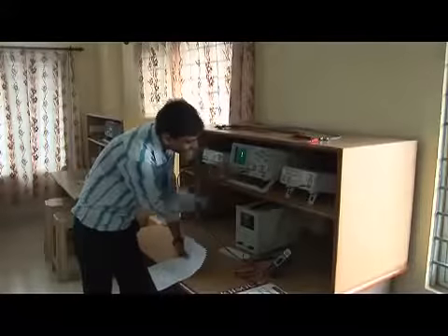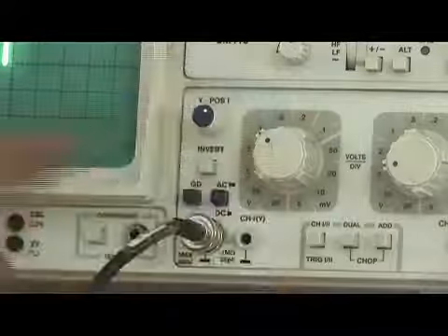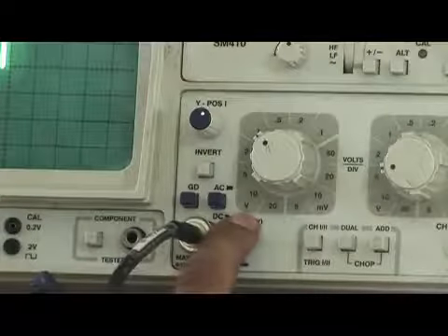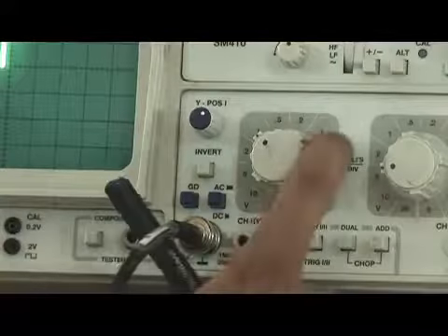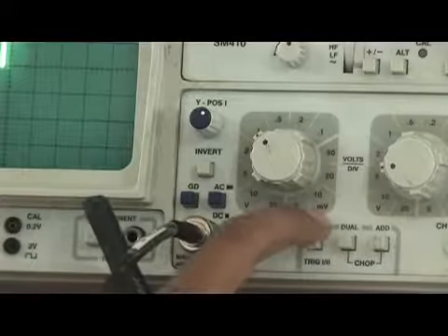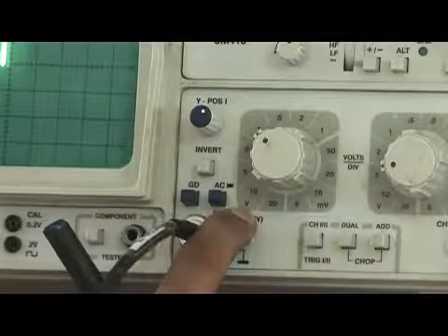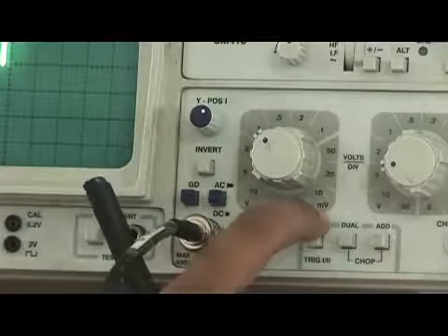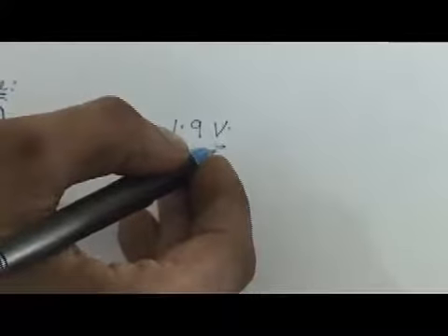So why is this volt there? Because here you can see from this bigger gap till this bigger gap, you have different magnification units with a value of volts. See, V is written. So this V denotes volts. From this bigger gap to this bigger gap, on the right-hand side you can see this is mV, called millivolts. That's why whenever this knob is in this range, you have to use the unit volts. When this knob is from here to here, somewhere in between, you have to use the unit millivolts. So in total, we are getting the amplitude to be 1.9 into 1, which is the magnification, equal to 1.9, and the unit is volts.